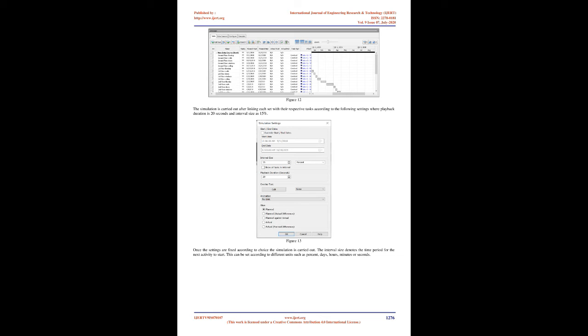Project demonstration. We have carried out the entire program using computer software and programs. Screenshots were taken at each stage of the project for demonstration. We used the Revit software to create the three-dimensional model of the building. Floor plans. We then transferred the 3D model from Revit software to Navisworks Manage software for linking the time constraints and its simulation. We then transferred the MS Excel file consisting of the construction schedule, tasks, and their respective details such as start and finish dates in the CSV file format.